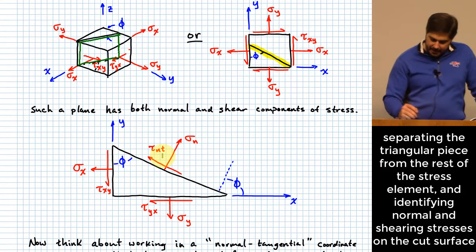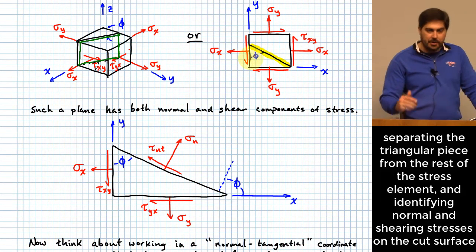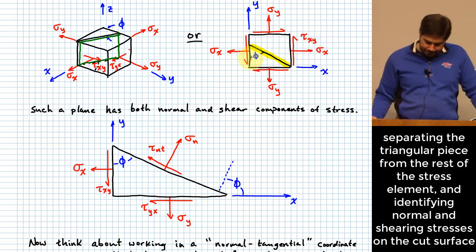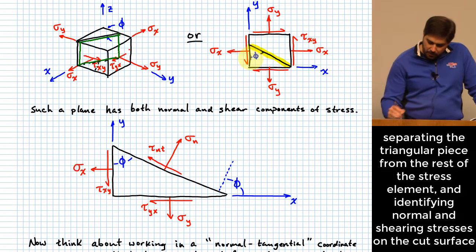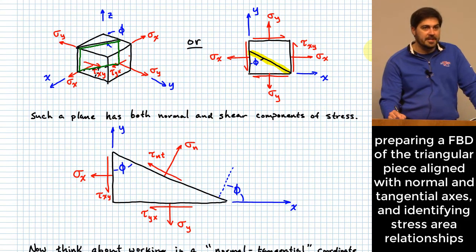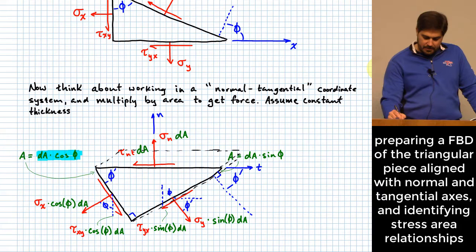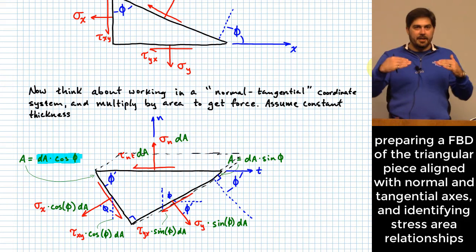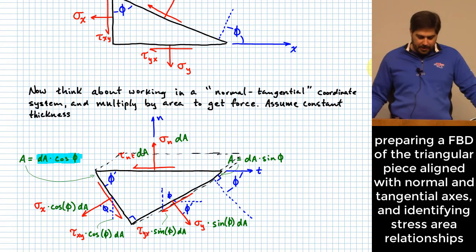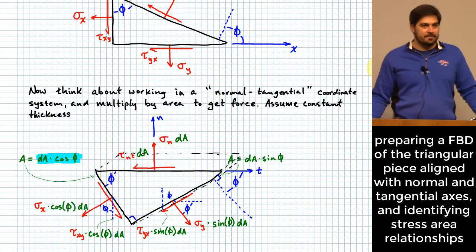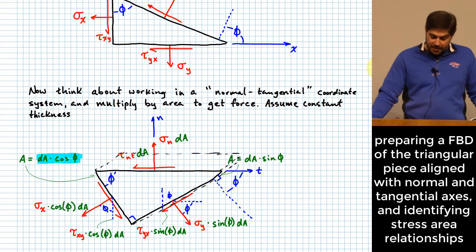All right, and further, we have this angle that describes how far we have rotated this coordinate system. Okay, that angle phi. That is what we're going to work with, but we're going to take that and now orient it such that my normal and tangential coordinates are aligned normally relative to my page, and that helps me see where these other stresses applied would act. This is where all the business gets done, right here on this figure, of doing the transformation into this new coordinate system.